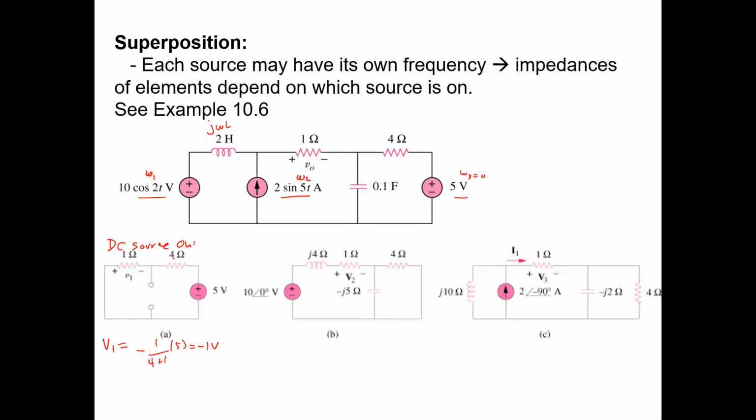The voltage V1 for that 1 ohm resistor, the minus sign is kind of on the high potential side, so it's going to be negative, right? Losing energy over there. The current is sort of flowing in the minus sign, coming out the plus sign. That's active sign convention. So we have a negative voltage drop there.